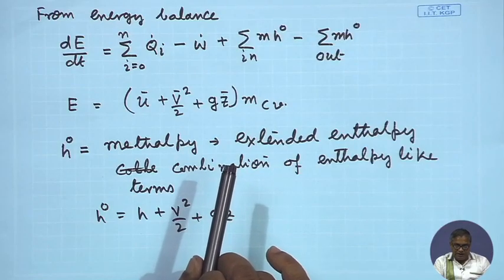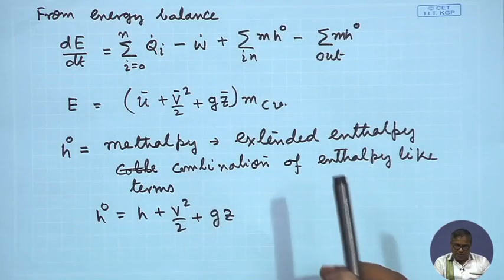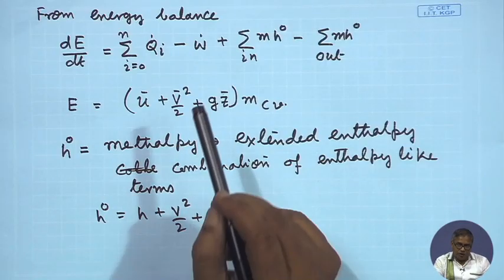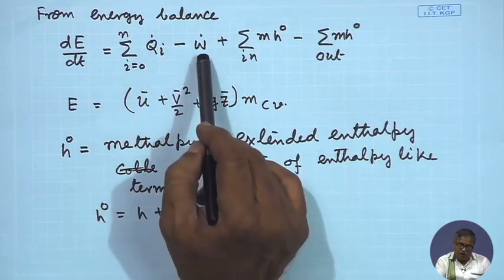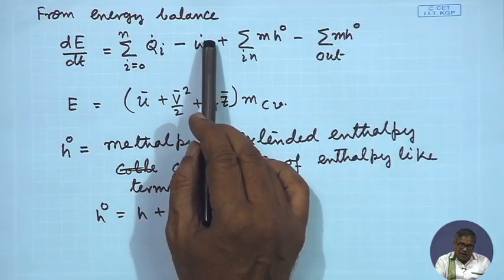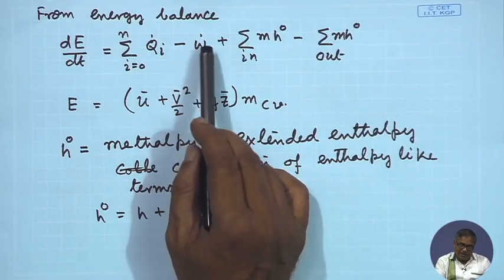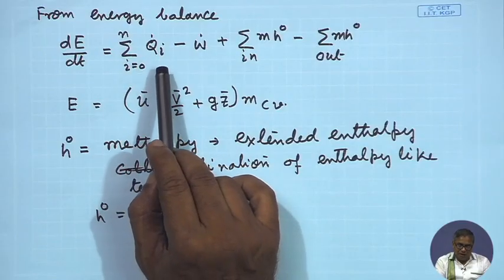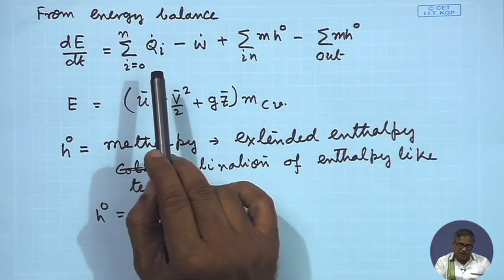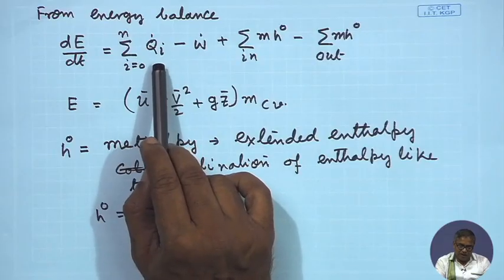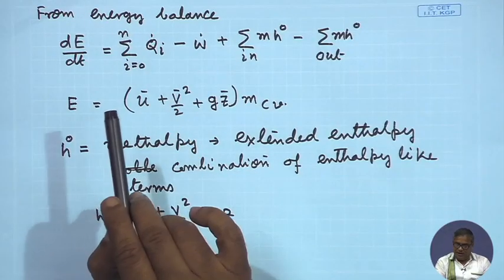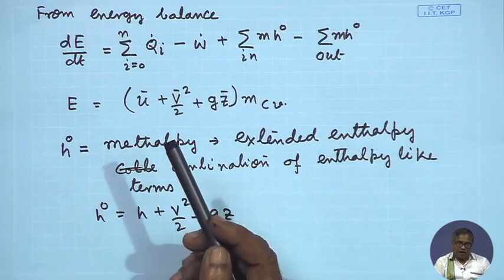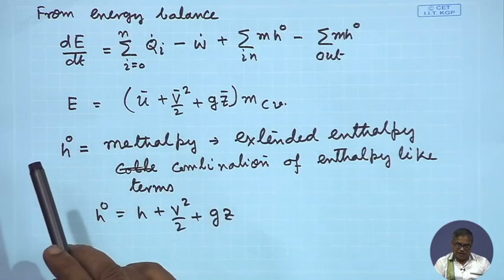You know that energy in transit may have two different forms: either heat or work. So, work done is denoted by a single term, and heat transfer is a summation term depending on the temperature at which heat transfer is taking place. So, we can differentiate them, particularly when we introduce the second law of thermodynamics.